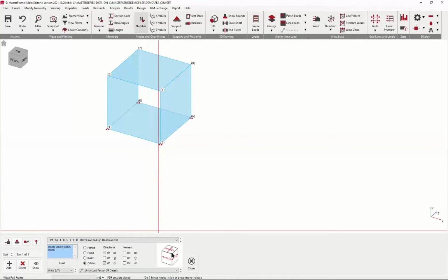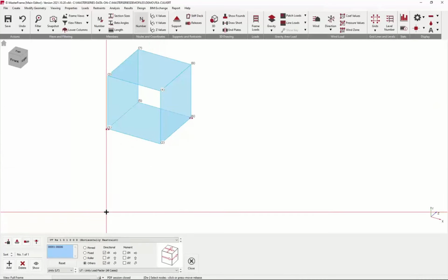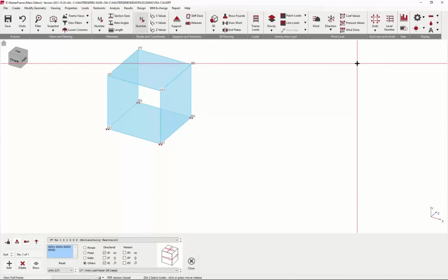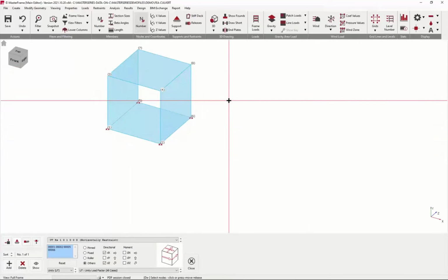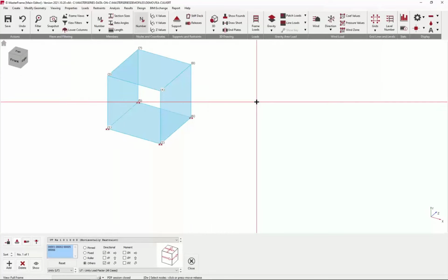Now you could get pedantic and say, well, actually you only need it at two separate points, and you probably don't need that in both cases, and that's going to give you the stability you want. So you do need at least one support in each of those two directions. That gives you resistance to prevent your structure just moving along the page out of the way.